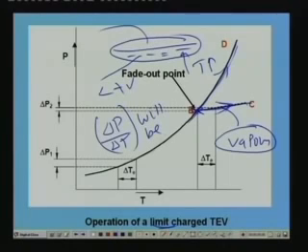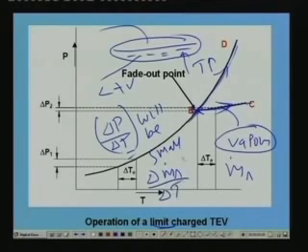This is small means what? The needle opening will be small. The needle opening will be small means mass flow rate of refrigerant doesn't vary much. That means from beyond this point onwards, if you write, let us say, delta mass flow rate divided by delta T, this will be small, because from this point onwards you don't have any more liquid, right?